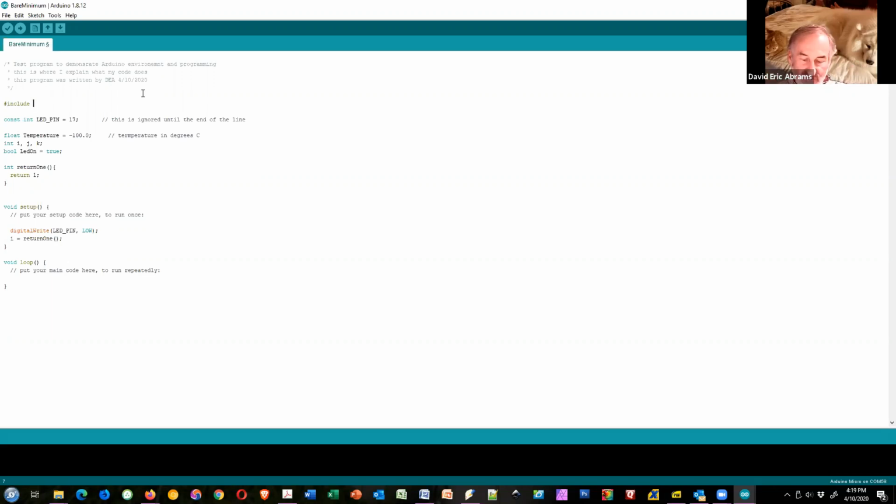And include takes an argument that's in left-right pointy braces, and that's the name of another file. It's a file on your computer. Some of those are there, but you don't even know it. For example, the one we are going to, I don't think we're going to use because I didn't send you home with the accelerometer, is called wire.h.